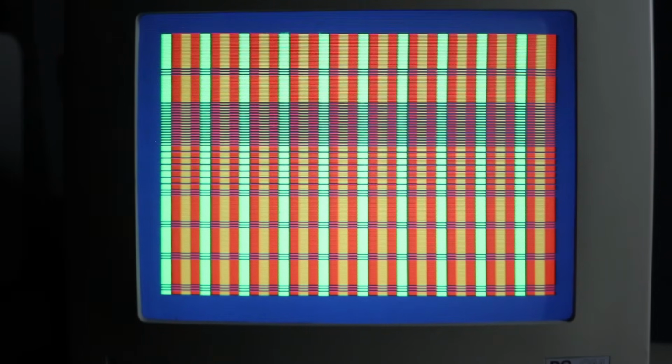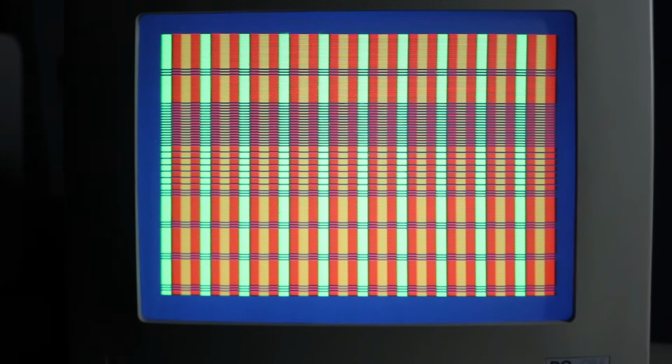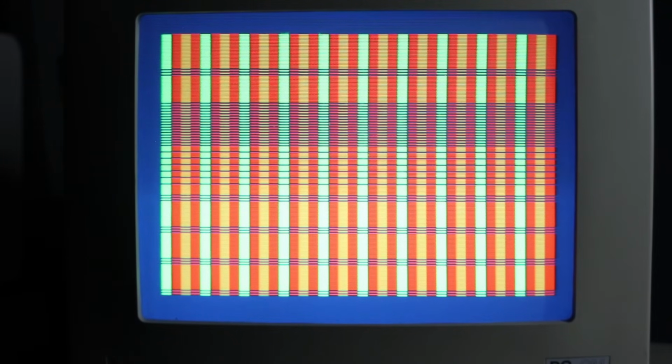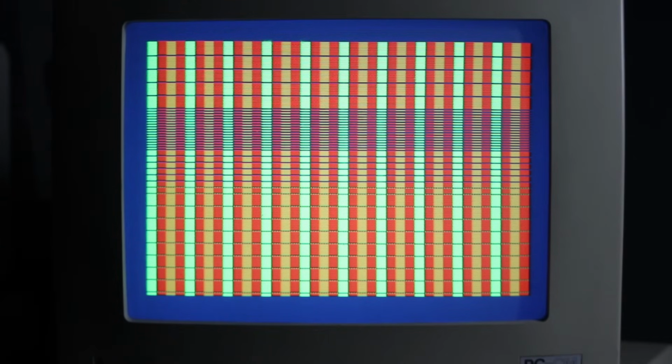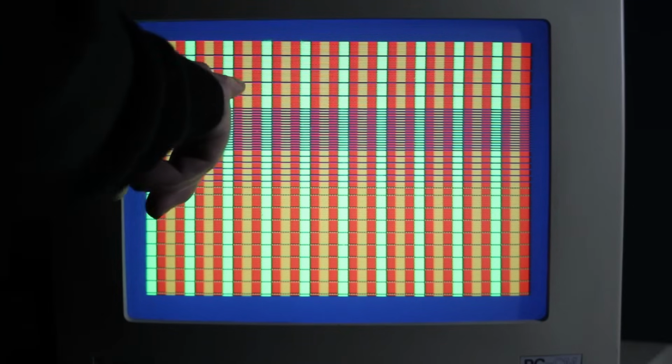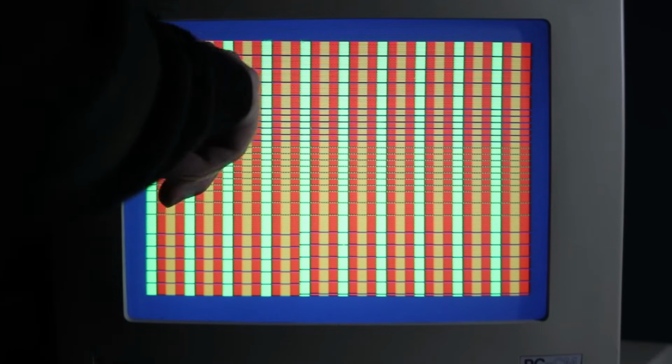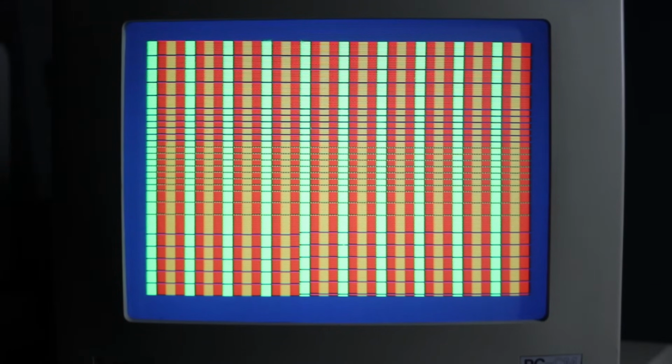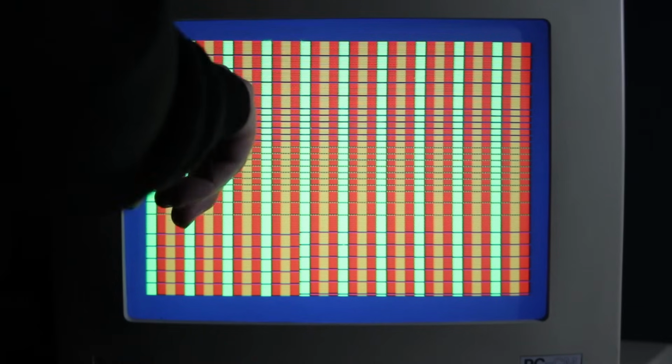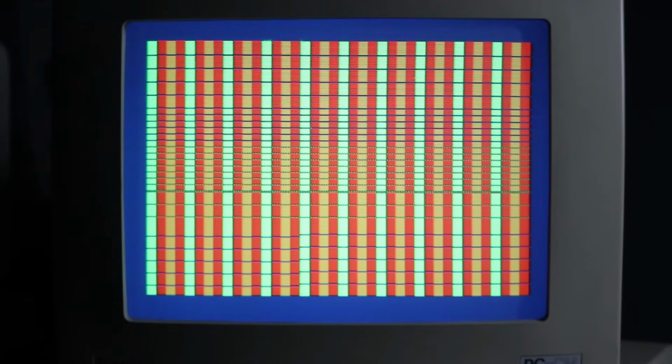So yeah, apart from that glitch, which will be interesting to look into, this is the behavior that you expect in ordinary CGA. Well, I already managed to figure out what causes this glitch here, and it happens on the PC as well, actually. So it happens when you're changing from a higher to a lower number of scan lines per character row, and if you've already passed the lower value, its only choice is to keep counting until it wraps around.